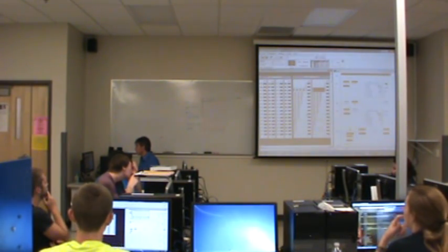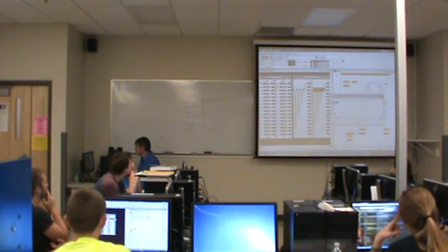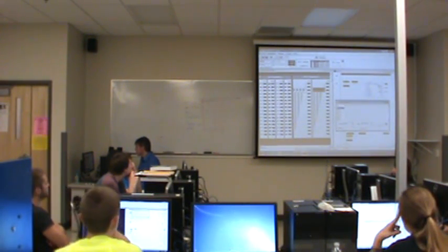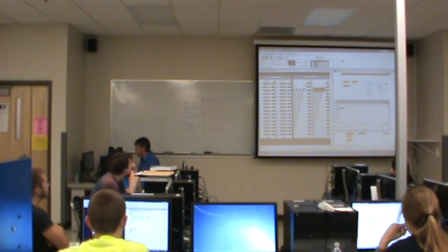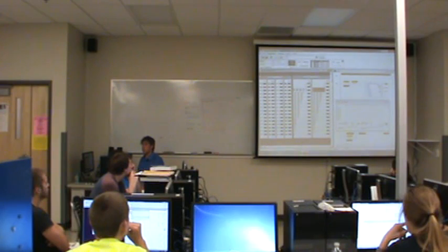Anyway, now let's increment this. So it's looking for input 5. This instruction is looking for input 5 to look like this. It wants to see this bit right here on. When I increment that wheel, that comes on.